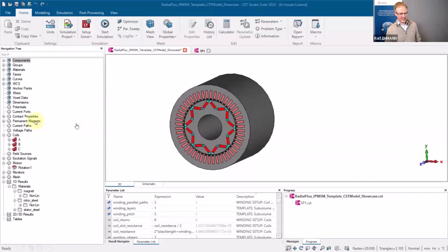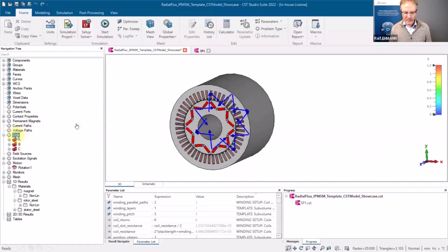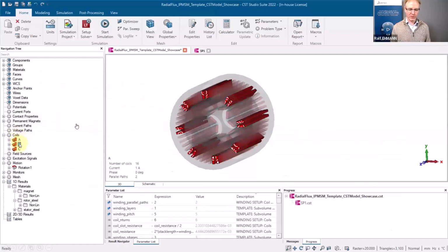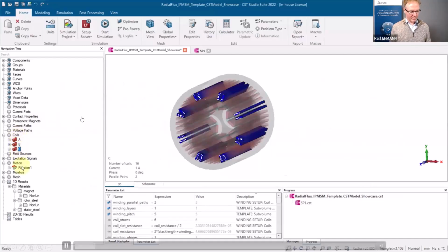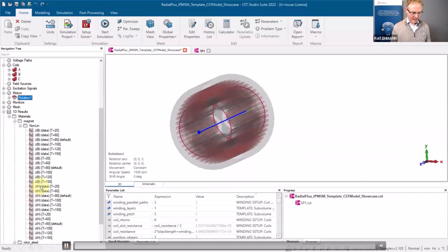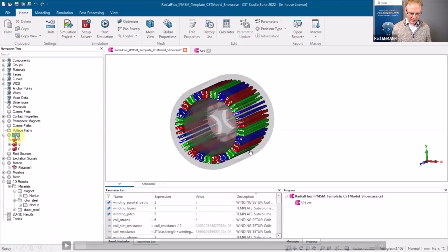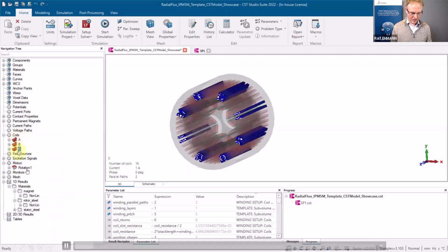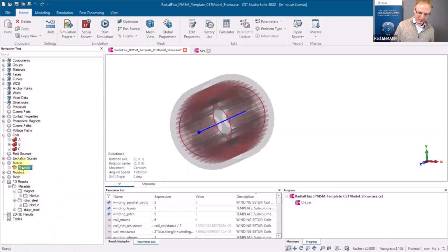Okay, having said this, I want to show you what it means to create an FMU in CST. So first, you have to define a valid machine simulation setup, and this means in particular you need the geometry. You have to set up excitations. You have seen already, I was going through the individual parts. So you need coils with a winding scheme. You need a rotation, was the next thing chosen here. Rotation means you have a cylinder just defined by a radius, being exactly in the air gap.